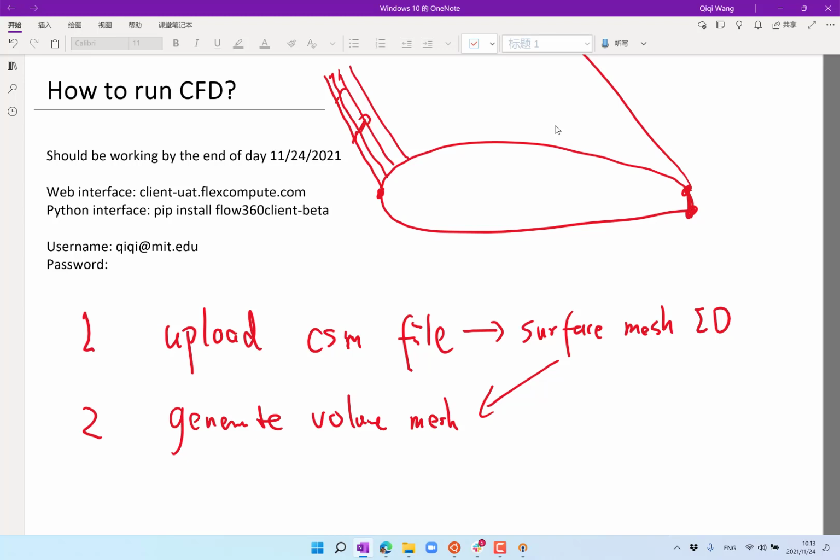In your CFD calculation, it's best to set this first layer thickness to be a small fraction, let's say 10% of the leading edge radius, so that you're resolving the curvature of the leading edge well. That's actually something pretty important to run a good CFD. If you don't get it in the first shot, when you run a simulation, it's pretty easy to identify that the leading edge is under-resolved, and I can always help you look into that. So once you start it running.